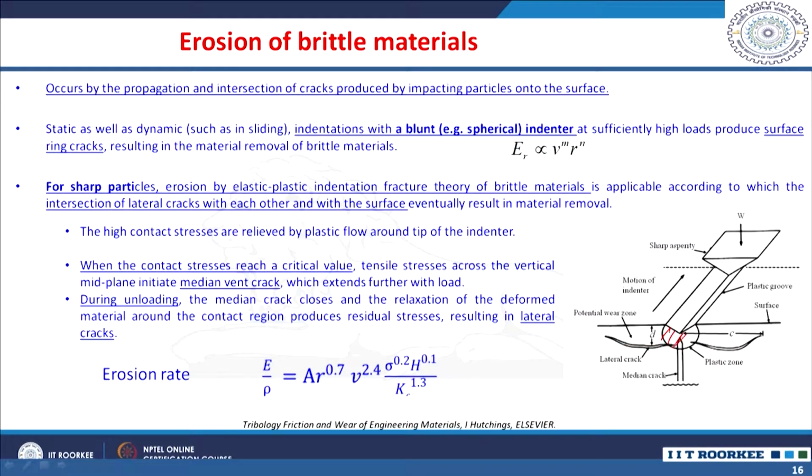So, when high contact stresses are relieved by the plastic flow around the tip of this indenter, I mean the particle with a sharp edge, right, with a sharp edge. When the contact stresses reach a critical value, tensile stresses across the vertical mid plane initiate this median vent crack which extends further with the load.